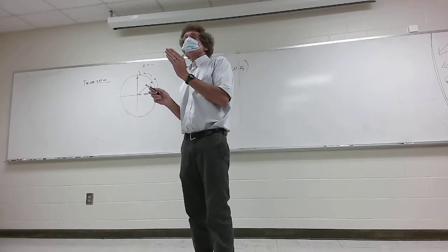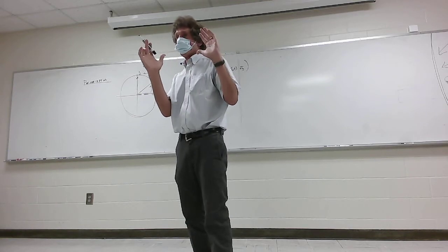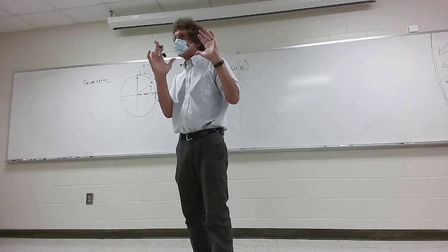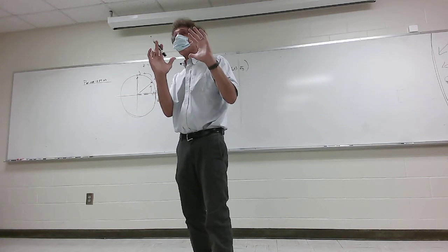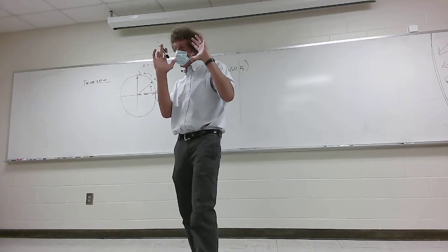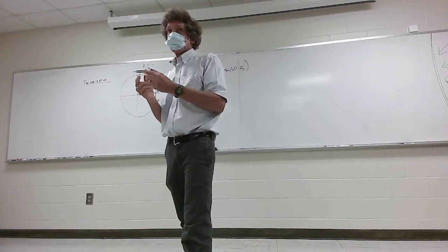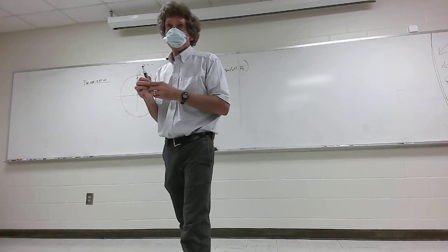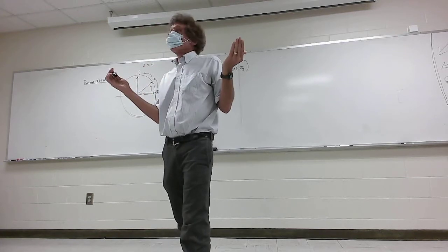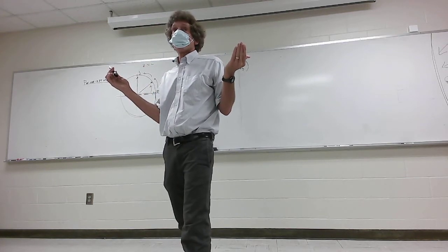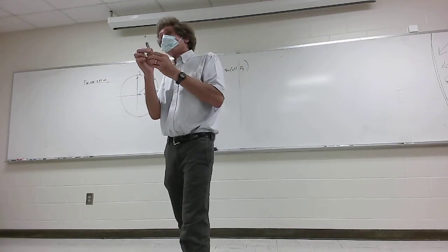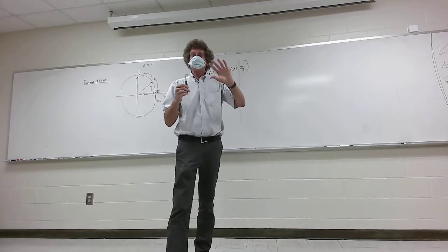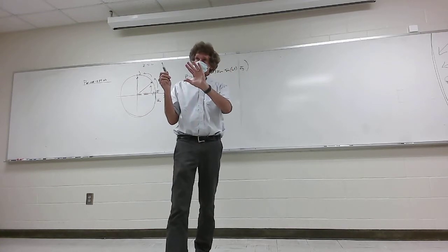The reason is discrimination. I work with radar. I've done electromagnetics my whole career. I've done a lot of different aspects of it. But with radar in particular, this is important. Because if I send out a right-hand circularly polarized wave, and a guy tries to jam my radar or spoof me with a right hand, I know that ain't from a reflection from a real target. I know he's lying. So what happens is I send out my wave, right-hand polarization. This is oversimplified, but in essence, it's the truth.